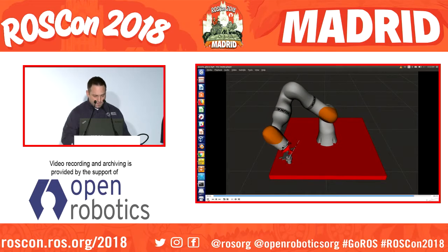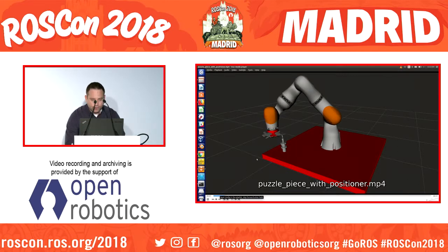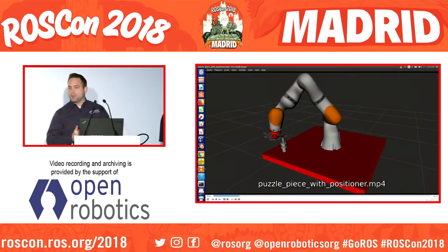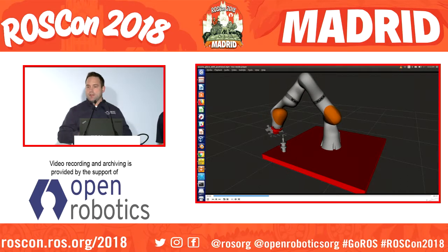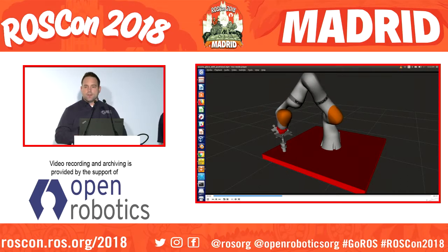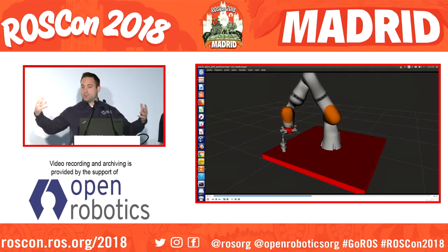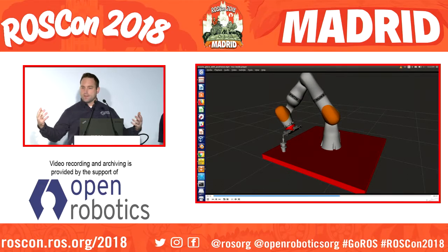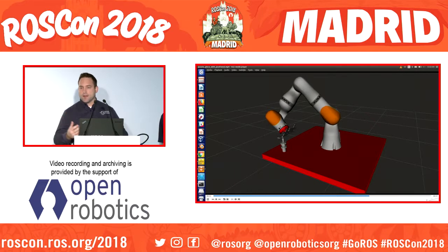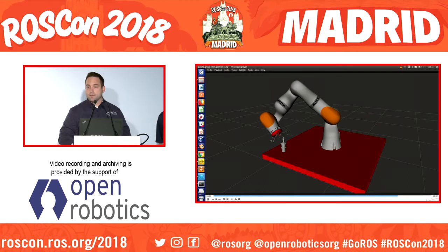And then we have another one, just to show that we added more. Say you have a positioner, a 2 degree of freedom positioner that allows the spindle to move. You want to solve that all together. So we created not only kinematic chain capabilities, but an arbitrary joint tree to be able to solve that. Say you have multiple robots in your environment, and you want to optimize them all together for a complex process. By using TrajOpt along with Tesseract, you have the ability to do that.